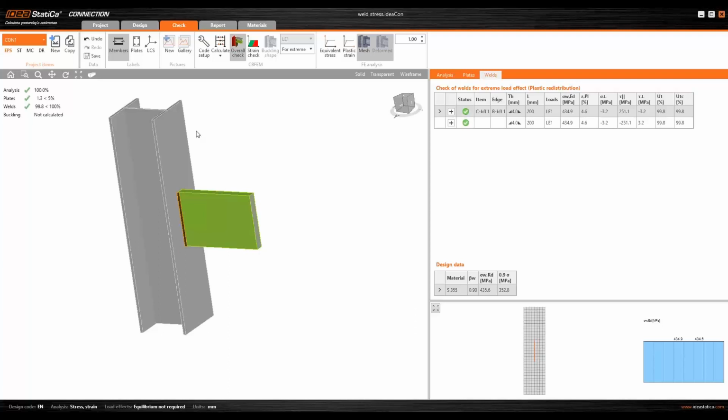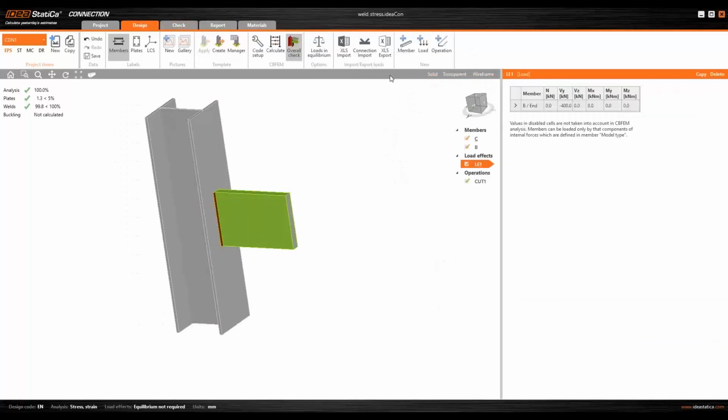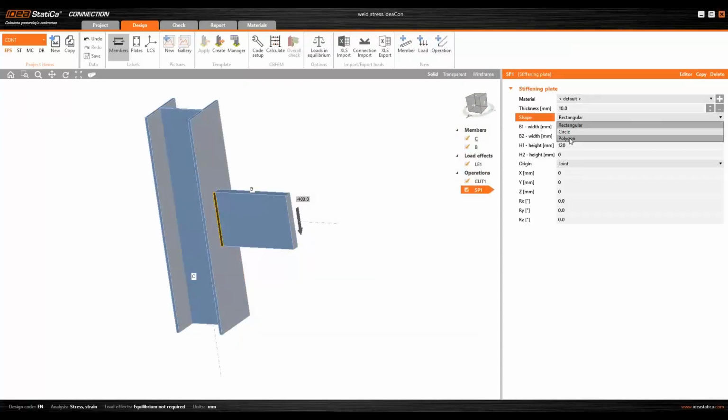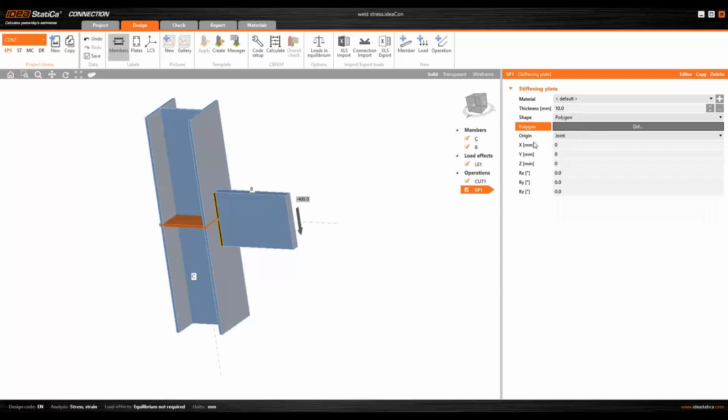So if you have it in AutoCAD, for example, as an object, you have to explode it out to just simple lines, and then you're able to import it. Another error comes when you don't close the DXF file before you import it, because when it's opened, you cannot read it with IDEA.